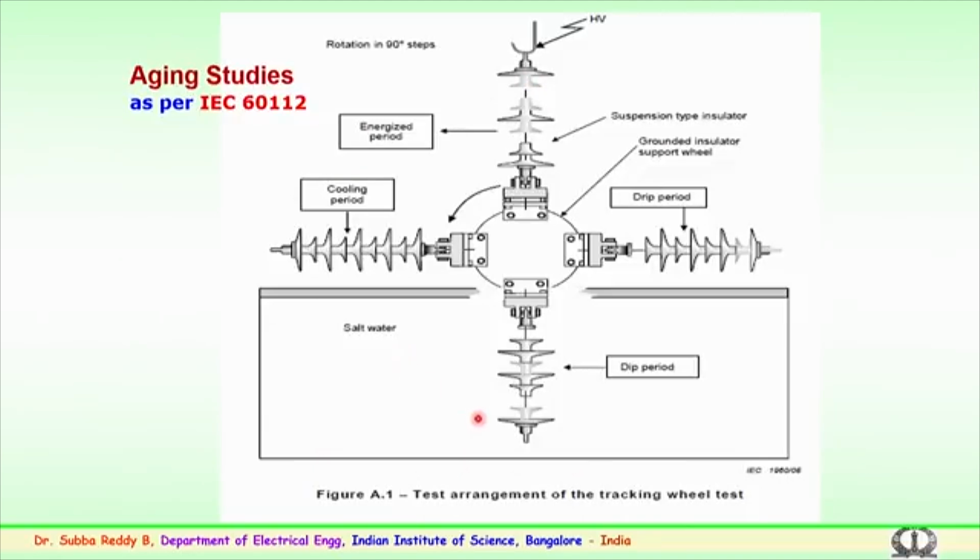So, 192 seconds corresponds to one cycle. Such cycles are conducted for more than 1000 hours. So, this could be 30,000 or more cycles which have to be conducted. This sample undergoes the experiment continuously for 43 days, or 1000 hours plus. During the process, in the contact or energized period, we have also tried to measure the leakage current, to see whether the leakage current gives some information.